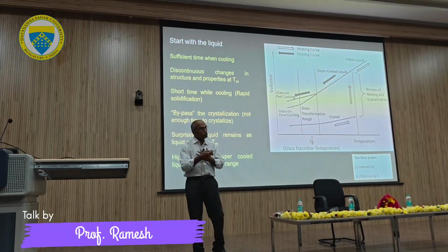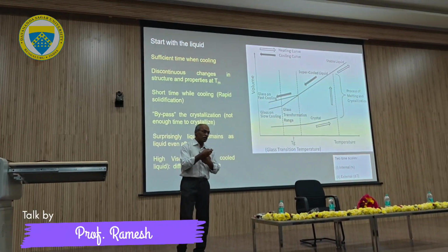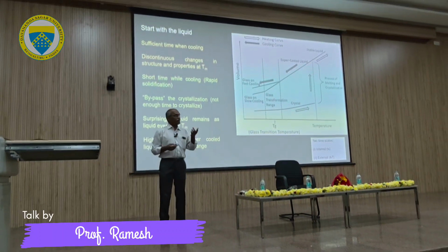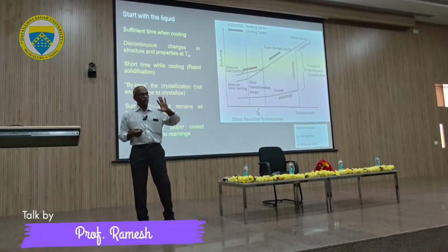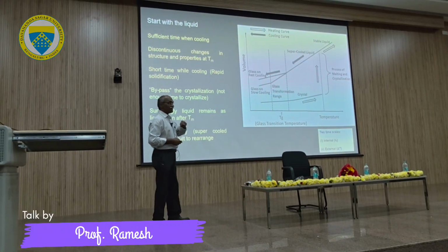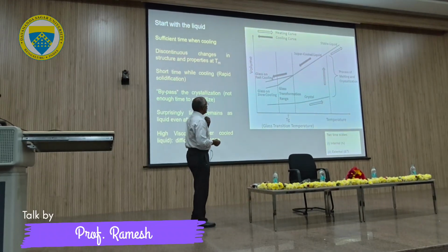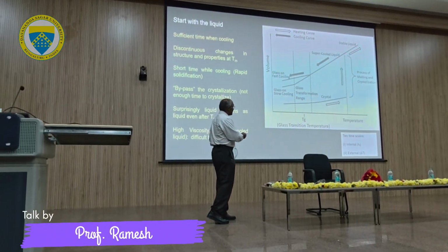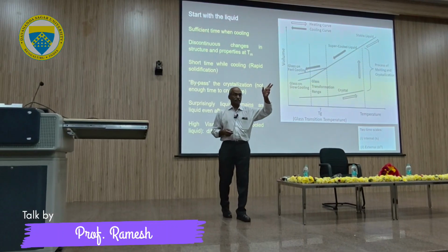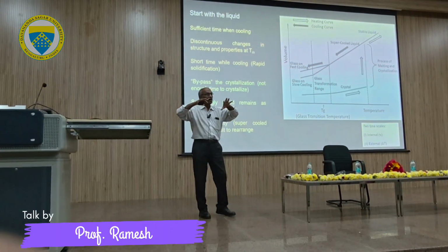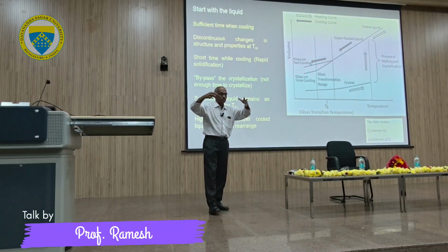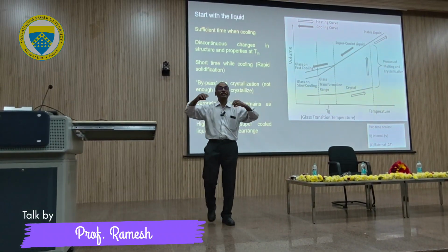When you cool the liquid, the other property of the liquid is viscosity, right? Viscosity is inversely proportional to temperature. Viscosity is resistance to flow. So when you decrease the temperature, viscosity will increase, so the atoms' movements are restricted. In a liquid, at high energy, you have a lot of energy for the atoms, so they will be randomly moving here and there.